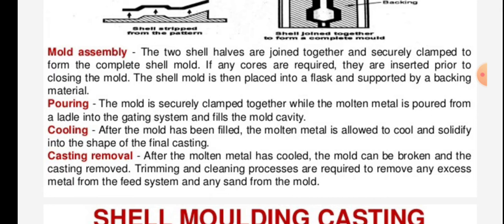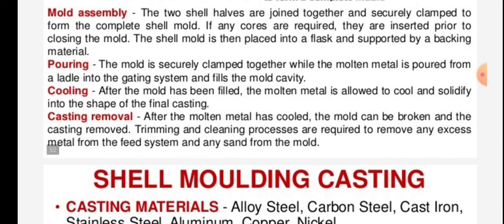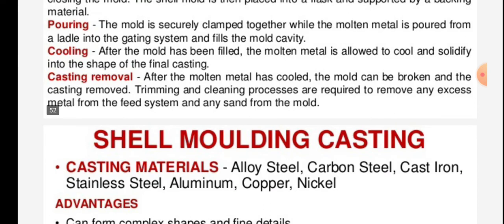Pouring. The mold is securely clamped together while the molten metal is poured from a ladle into the gating system and fills the mold cavity. Cooling. After the mold has been filled, the molten metal is allowed to cool and solidify into the shape of the final casting.